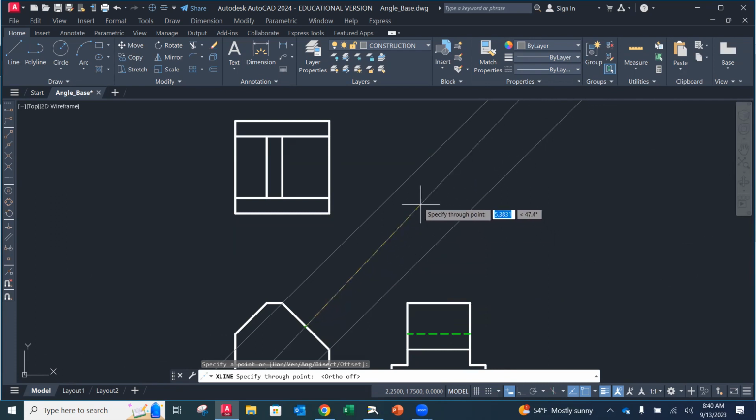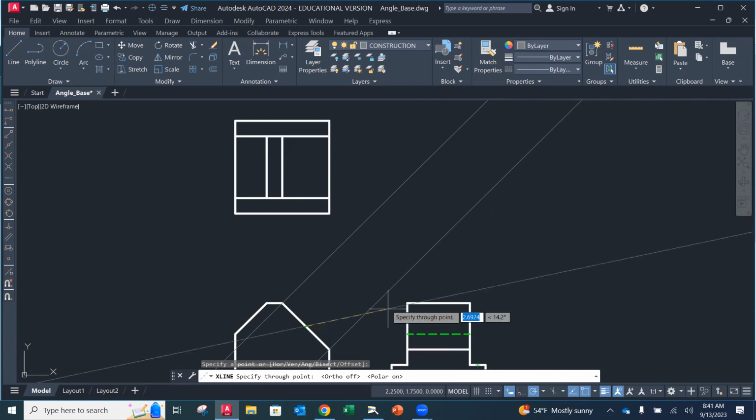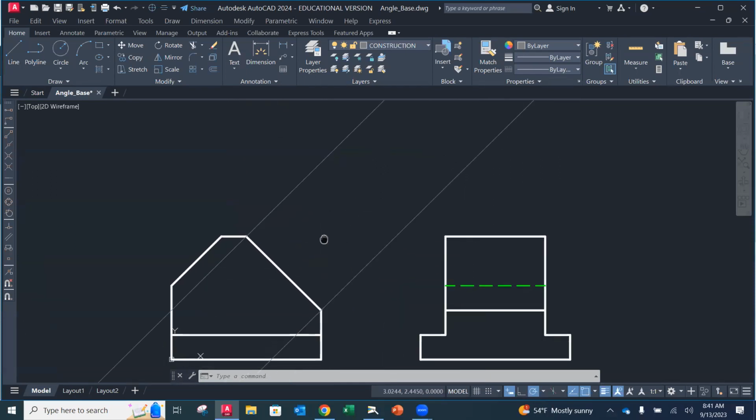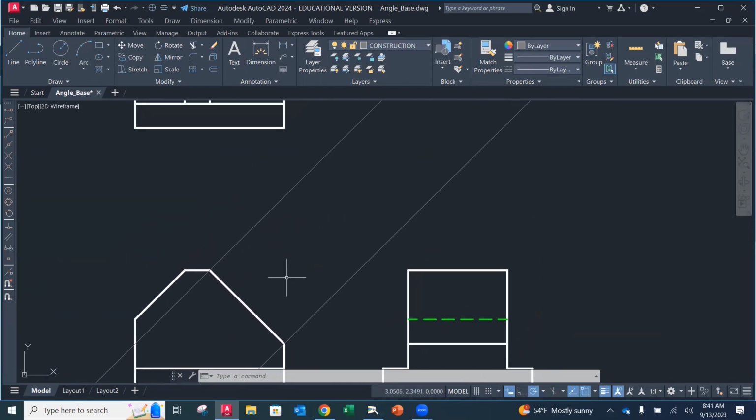So now when I get to, now why isn't it doing it? Oh, I did. Thank you. I was going to say, what the heck? So when I get close to that, in this case, 45-degree angles, notice that it grabbed in there and it snapped to it. Or if I get close to a 90-degree angle, it's snapping in there. Okay. So yes, polar tracking. Thank you, Emily. Great idea. Yeah, I didn't think of that one. There's probably 4 more that we could do as well. So all of these are tools that are at your disposal.